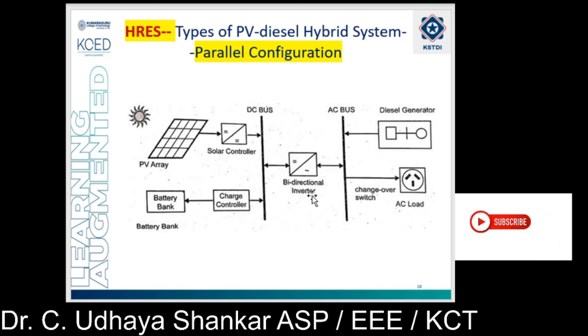This is one of the new concepts in the power electronics industry, that is the bidirectional inverter. It takes care of synchronizing, switching, DC to AC as well as AC to DC, everything. That's why it is called a bidirectional inverter. The only thing is it is very costly when compared to the previous configurations, but it is more suitable for industrial applications as well as hospital applications.